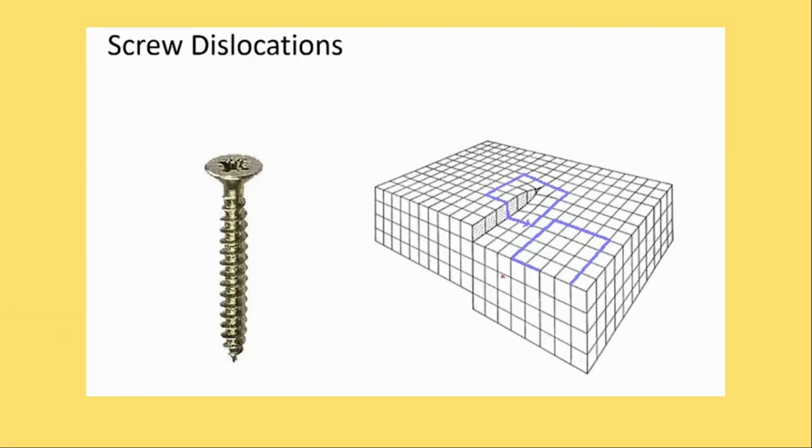Let's suppose the stress is being applied here, like this. If we draw a Burgers vector around this, 1 2 3 4, 1 2 3 4, 1 2 3 4, and 1 2 again. There's an open loop here that shows there's a dislocation out of the symmetric lattice. So what is the Burgers vector here? We can draw it from start towards the end. This is the direction of that Burgers vector, and this is the magnitude, one atomic distance.